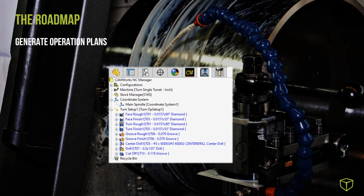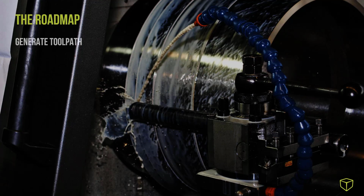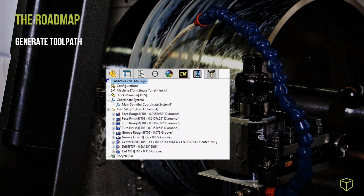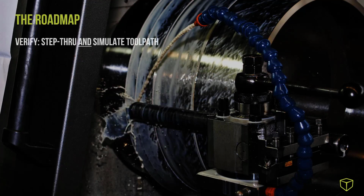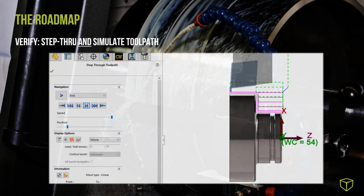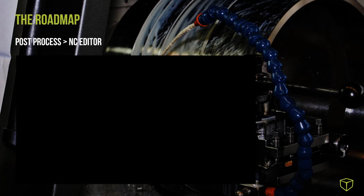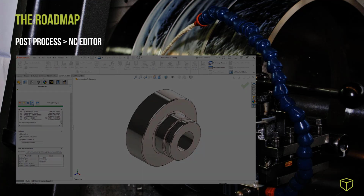Generate that information into operation plans. This contains how each machinable feature is to be machined and how the NC code will output. And from the operation plans, we'll generate toolpath to see how the cutting tool is used for that operation. Next, we will review our work by using the available verification tools, such as Step Through Toolpath and Simulate Toolpath. And finally, post-process and review the NC code.